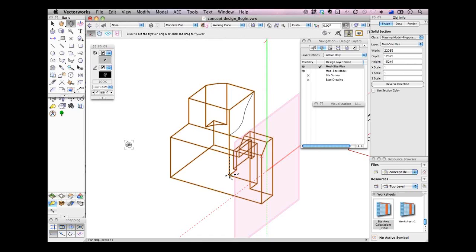Yeah, that's totally fine. This was back when you were filling the design. Are you filling with a class or moving into the class? No, you're moving into a class. The class controls the graphic style of the objects. So I think it's when I was using the polygon tool with the paint pot mode, the create polygon from inner boundary. You click and it fills that object up with your active class, which currently is none. You then go to the object info palette and change that to the class you want, and then it picks up the graphic attributes of that class.